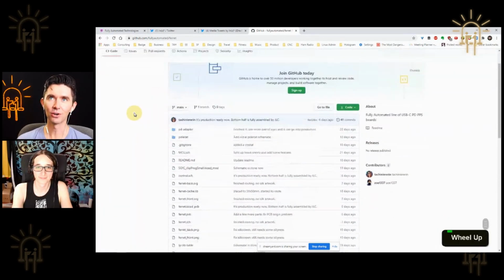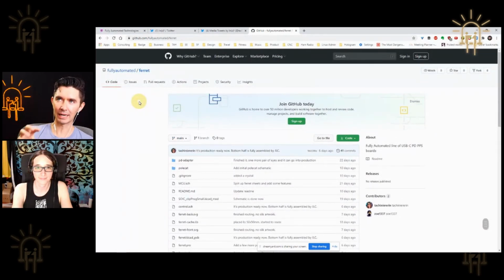So one last time on the project output here. It's USB-C, and then you can either plug in to get the power supply voltages, or what was the other mode? Um, so there's also fixed voltages. So there is a defined 5 volts, 12 volts, I think 15 and 20. And those are in the older standard. Those are the ones which compliant power supplies had to support before.